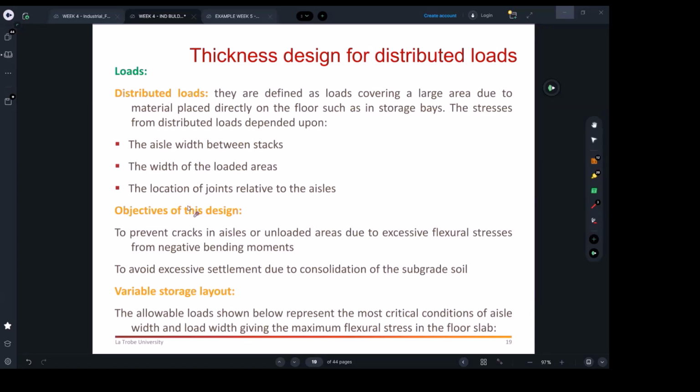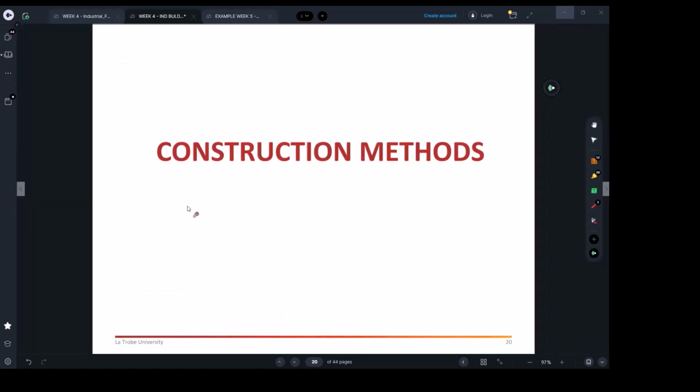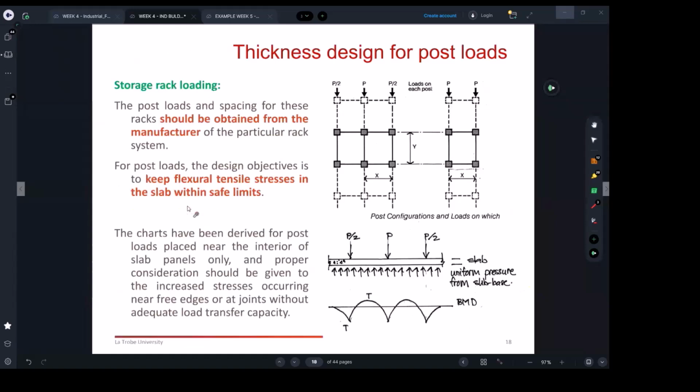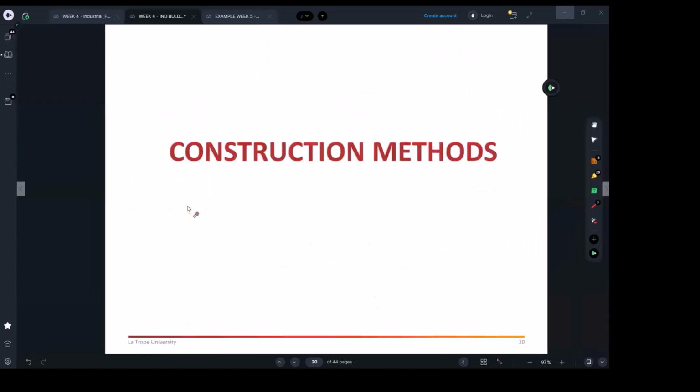It can also be during construction, because you're going to be using the slab, and one of the things is you may be loading it more than what the user is going to be doing to it, because maybe it was just a lightweight shopping or retailer where you don't have vehicles on top of the slab, like Coles, for example. Most of the time they don't use forklifts. They're just unloading and unpacking without vehicles. They just do it manually, just the trolleys. Okay, so that was the first part.